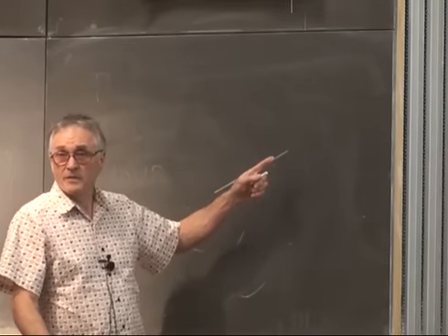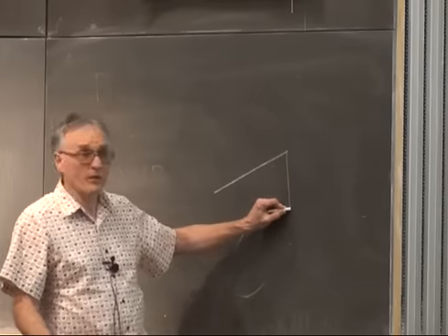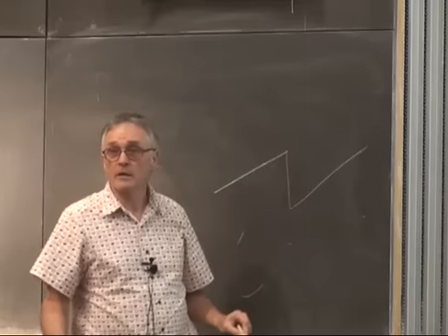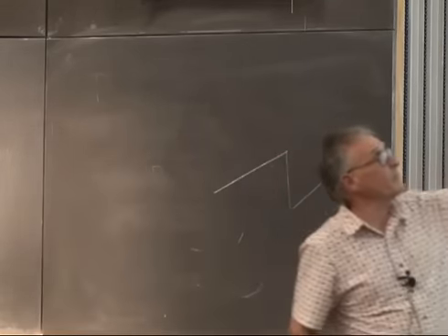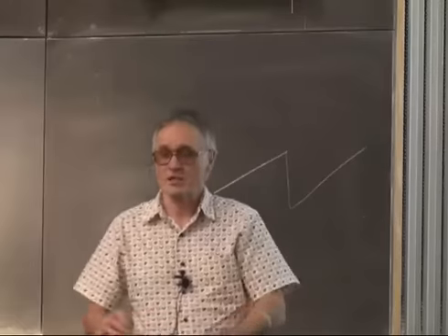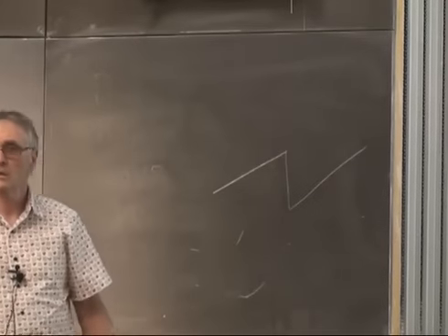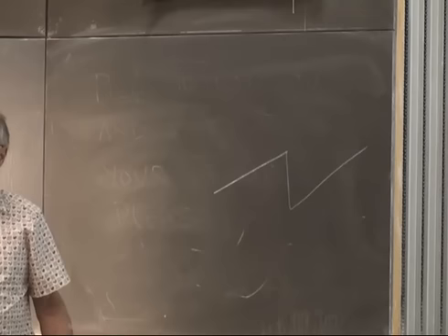The lower 12 bits are 0, and so the next cycle zeros the counter and it starts over again. So this is modulo 4096. This is equivalent to a mod 4096 operator, but much faster. Did that answer it or no?